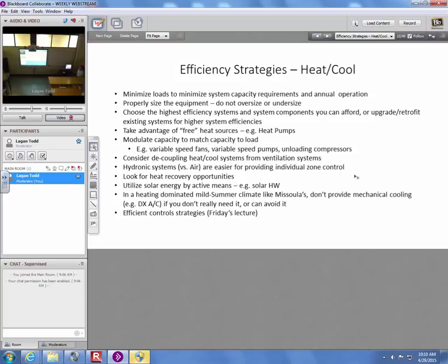If you've got a furnace or any kind of ducted air side system, how are you going to say, well, I need heating and therefore air at that bedroom, but I don't want any over in this bedroom? You'd have to have zone dampers all over the place, and then you're getting into a more complicated air handler system like we see in commercial, like a VAV system or something like that.